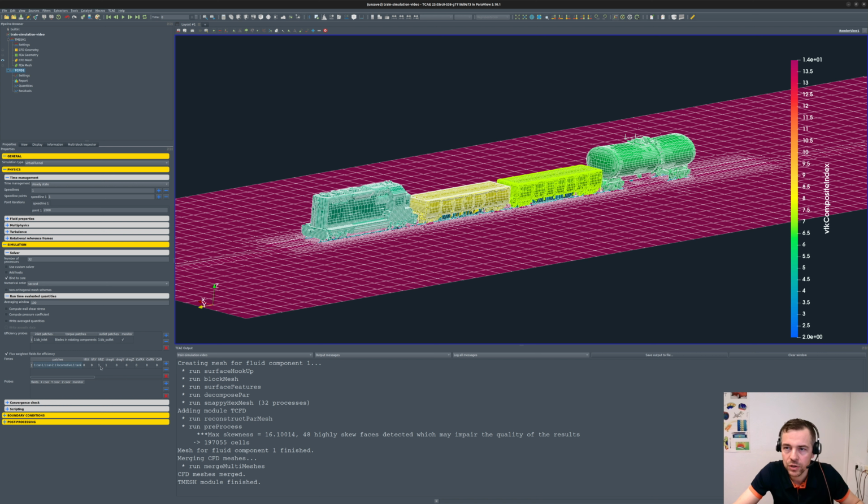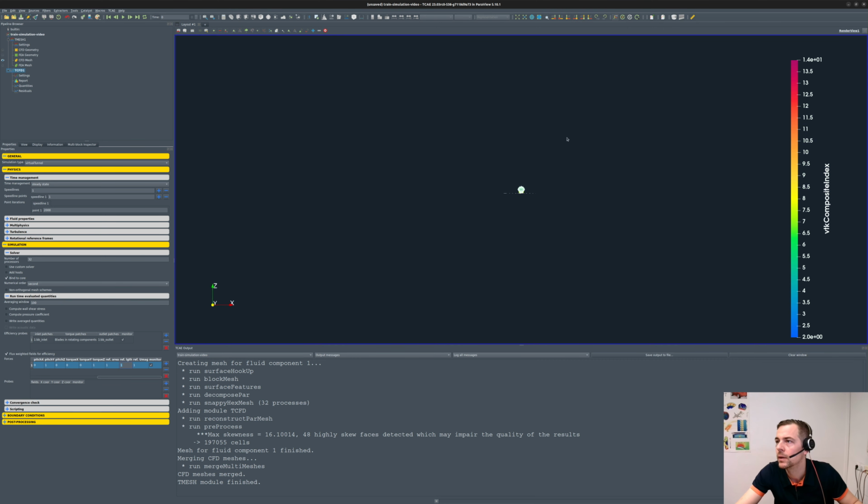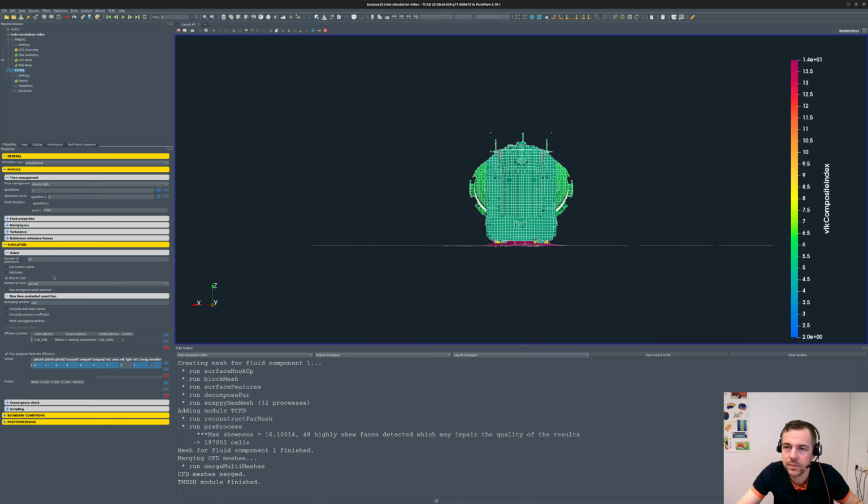I will let it integrate the forces acting on them. The lift direction is Z. The drag direction, it's important, is Y, and I also need to specify the reference area. It's approximately 5 meters times 5 meters, so it's 25. Sorry, not this.